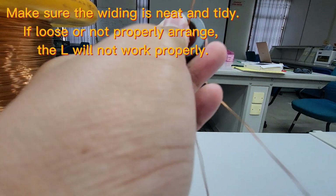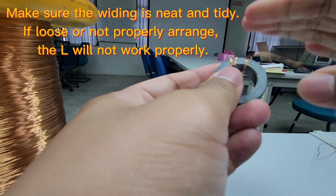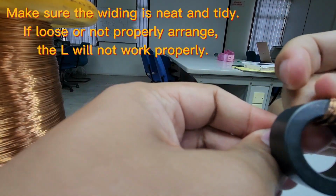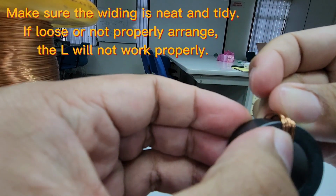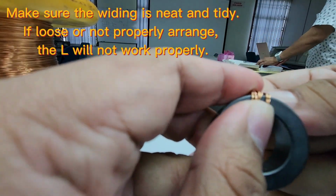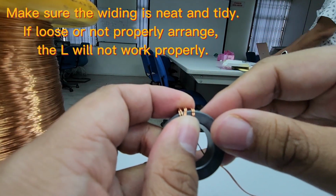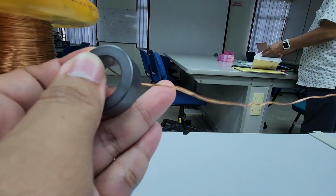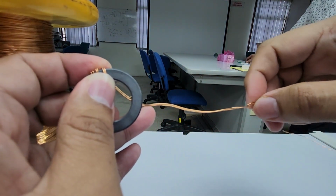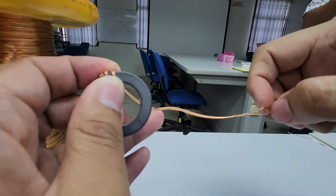Make sure it's tight. If not tight, your inductor will have a problem. It will move. So it needs to be very tight, even the winding loop. After you tie it up, tight one by one, and then wind again. And after you make the winding, in this example it is 19, right? So at the end, maybe there will be extra here. After you wind 19 times, cut the extra, and then you remove the pin.